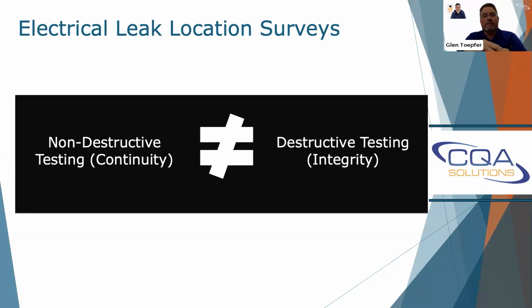But just think of a sheet of geomembrane. Say you have a sheet of geomembrane, 60 mil thick. You're going to do a leak location survey on it. You've got a conductive medium behind it, either on the sheet itself, so conductive-backed 60 mil, or you have a conductive subgrade below.